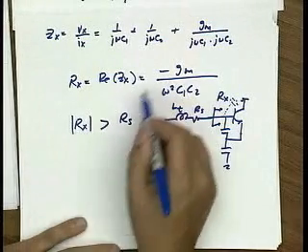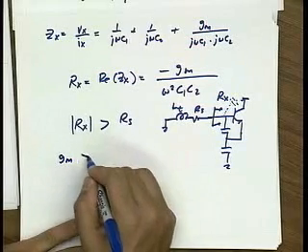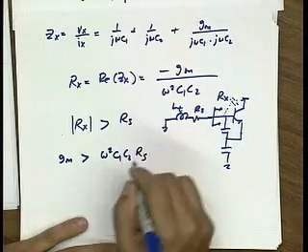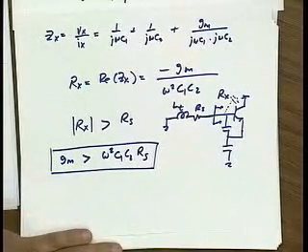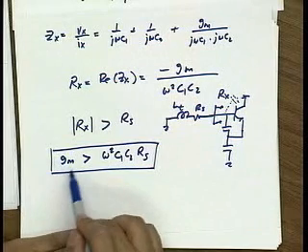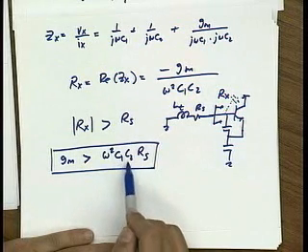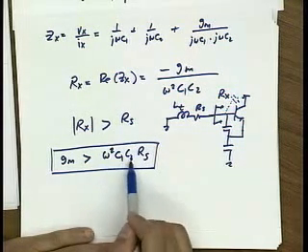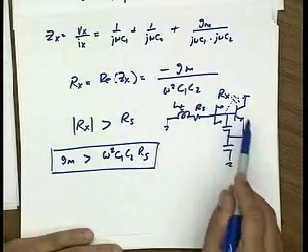So now, replacing here, we see that Rx bigger than Rs implies that Gm has to be bigger than omega squared C1 C2 times Rs. Which tells you that as you go to higher frequencies, you have to pump more current in your device to meet the oscillator startup conditions. Now you might think, well, Rs I can't do much about, right? That's fixed by the Q of the inductor. But I could always use smaller and smaller capacitors, right? But in the limit, you're going to hit the capacitors of your actual device.